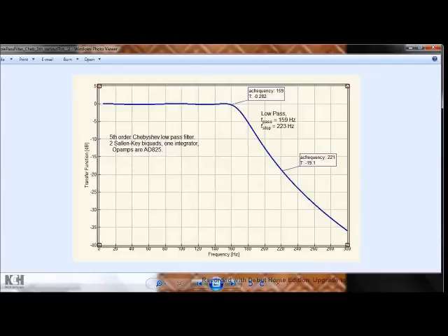Well, there you have it, a low pass 5th order Chebyshev filter based on the equal ripple profile. We showed the method of calculation with Matlab to find circuit elements. Then we ran a simulation in QUCS confirming the low pass frequency response.